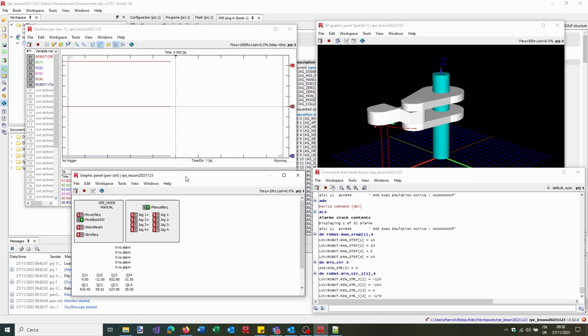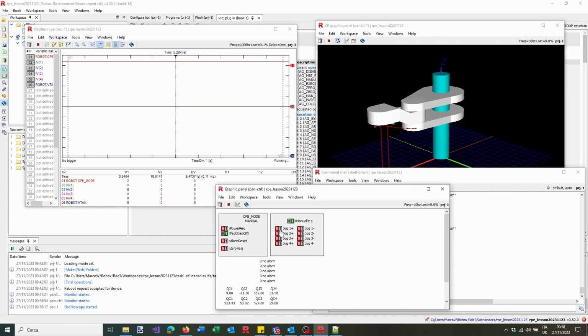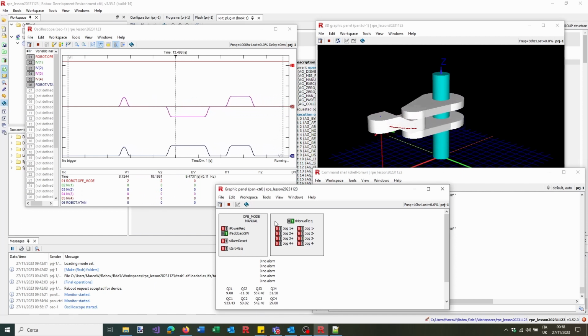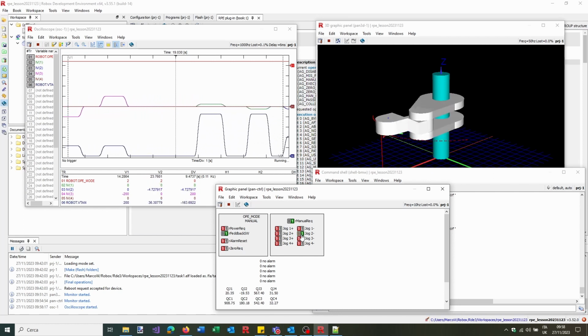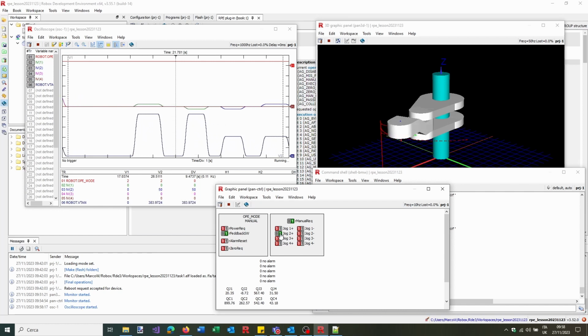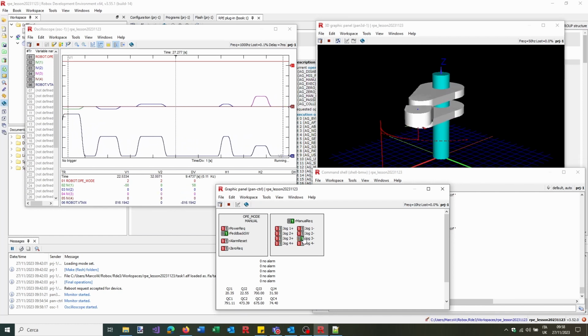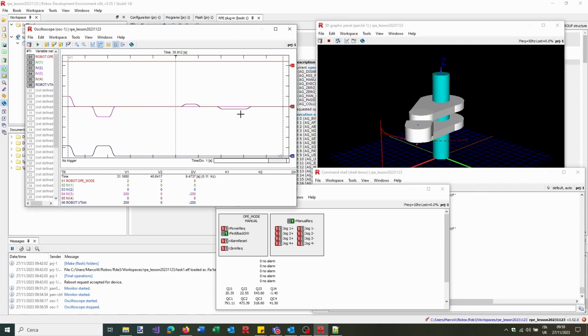So this is the most important value, let's say, because from here we know how fast the robot is moving. Now if I put it away, we can try to play again and move J3 up, J3 down. You can see that the motion is jerked. You can see that the speed is very smooth during the acceleration ramps. J1 minus J1, J2 minus J2 plus J2, and J3 minus J3, and J4 minus J4.